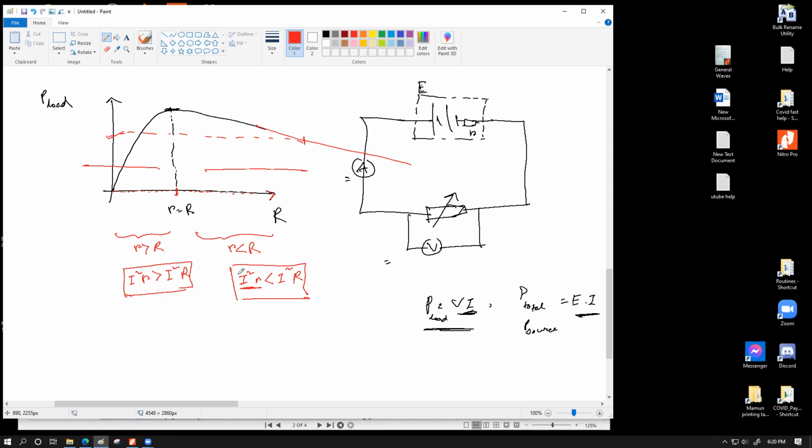But that's one side of the problem. The other side of the problem is that if you produce too much heat within your battery, you need to actually install cooling systems to your battery. Because if your batteries get warmer over the usage, that heat energy will introduce more resistance within the conductor materials. So you are simply going to keep on losing more and more energy. So it's basically like a vicious circle. So we don't want that.